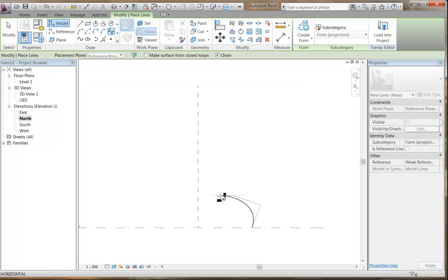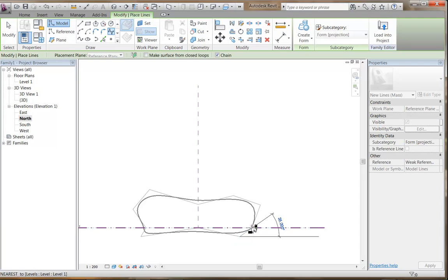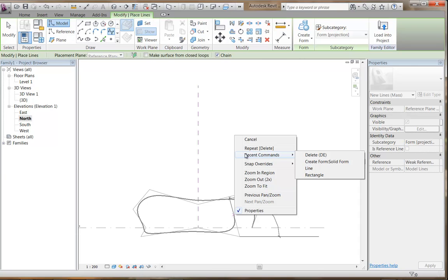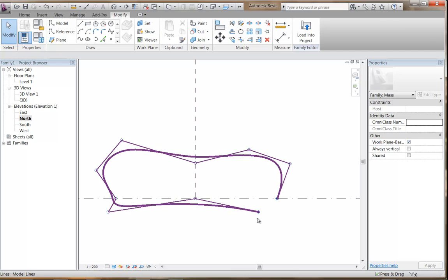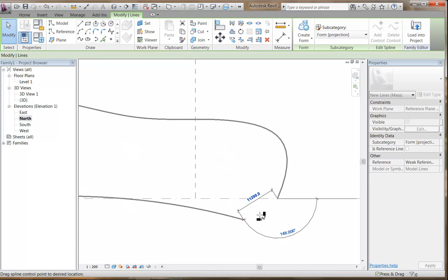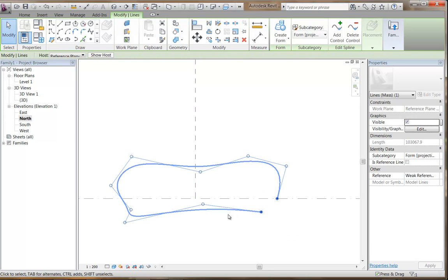you're doing a blend, which is basically what I'm trying to do, except it'll be better than a blend. I don't know if any of you remember the limitation with blends in Revit. There's really two limitations with a blend that I always found very frustrating. Okay, so the limitations are that the two shapes you use need to be in the same plane, also in parallel planes, so you can only blend between two parallel profiles.